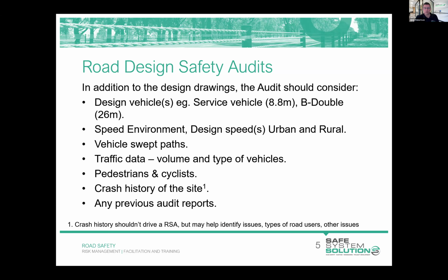Those that don't have a concern that auditors can get caught up in what's happened in the past and think that those crashes are the only type that might continue to occur going forward. So if you do have the crash history for a site, it's important not to put the blinkers on, so to speak, and really think outside the nature of crashes that have happened in the past, because there really is a high degree of randomness a lot of the time in crashes that occur.